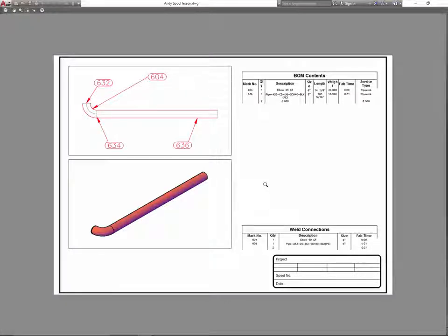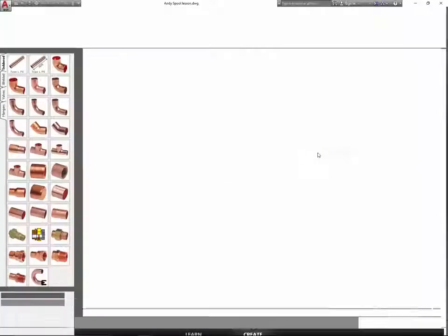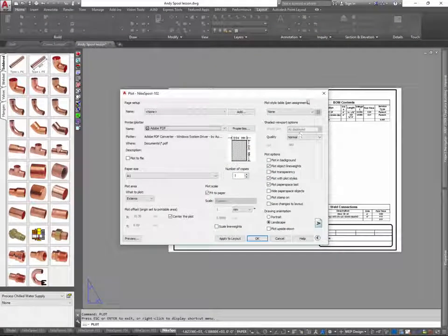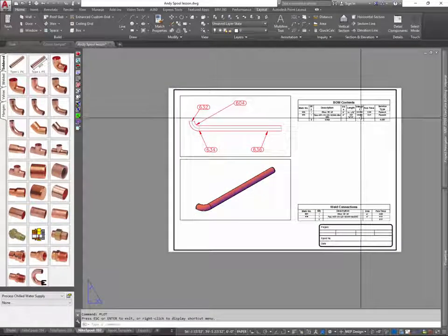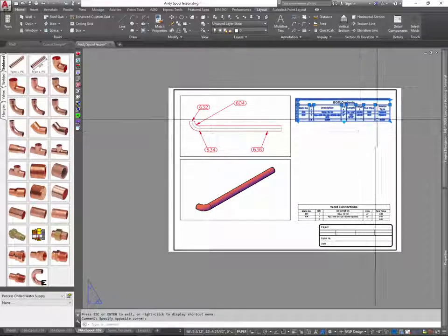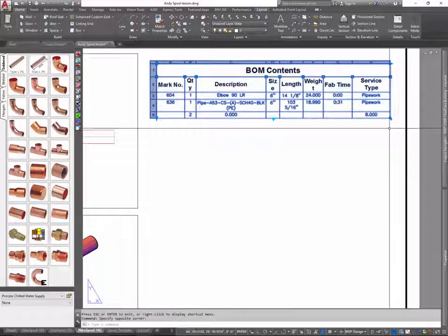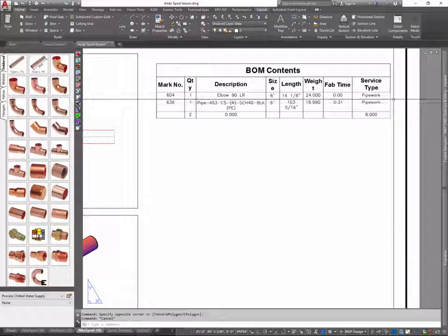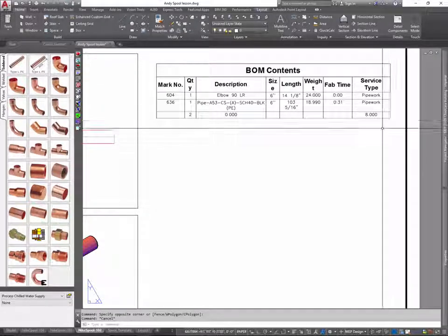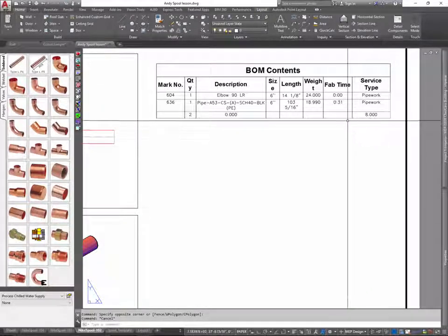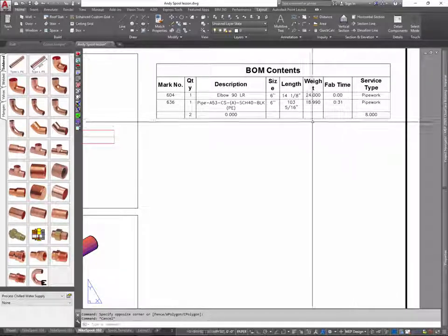I'll go ahead and hit my print preview, and what else do we want to do here? I think that's it. And oh, the tables themselves, guys, these are AutoCAD tables, and you'll notice that some of the line work is gray as opposed to being solid black here, and the gray ones I think don't print.